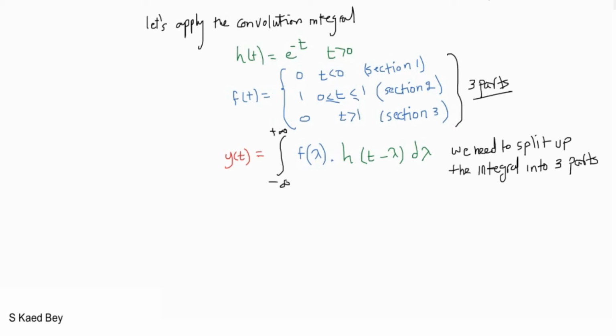The convolution integral shown here means reverse, shift, multiply, and add. The signal shown in green will be reversed. The integral limit is the actual shift, you multiply what's inside the integral, and simply the integral is addition.